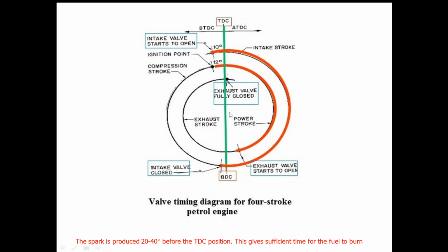Now draw an arc using a compass with an appropriate center till here, and you can see that the inlet valve will be closing after bottom dead center.